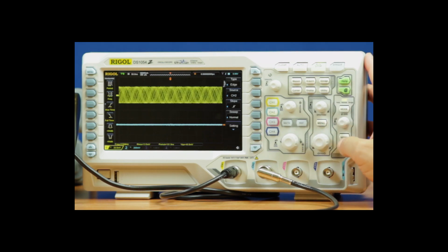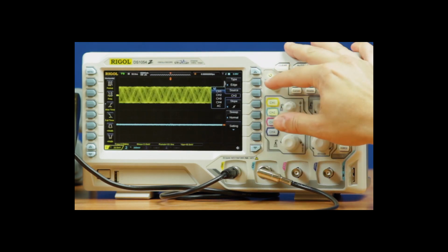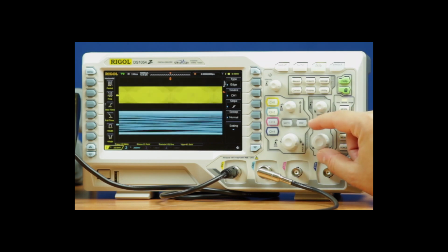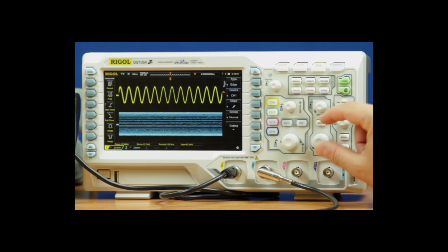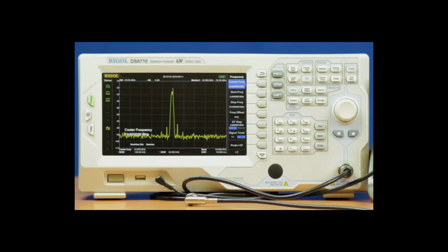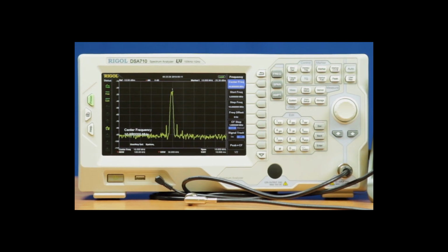And I can actually go ahead and switch over to trigger channel 1 if we want to see it directly. So those are those frequencies directly. We can see how it's changing beneath. But really, there's no settings on the scope where we can easily see the change in frequency because the two frequencies are just too close together. However, the spectrum analyzer is picking it up nice and easily because it's able to completely demodulate that signal, which we can see in the bits here as we move out to the 500 microseconds.